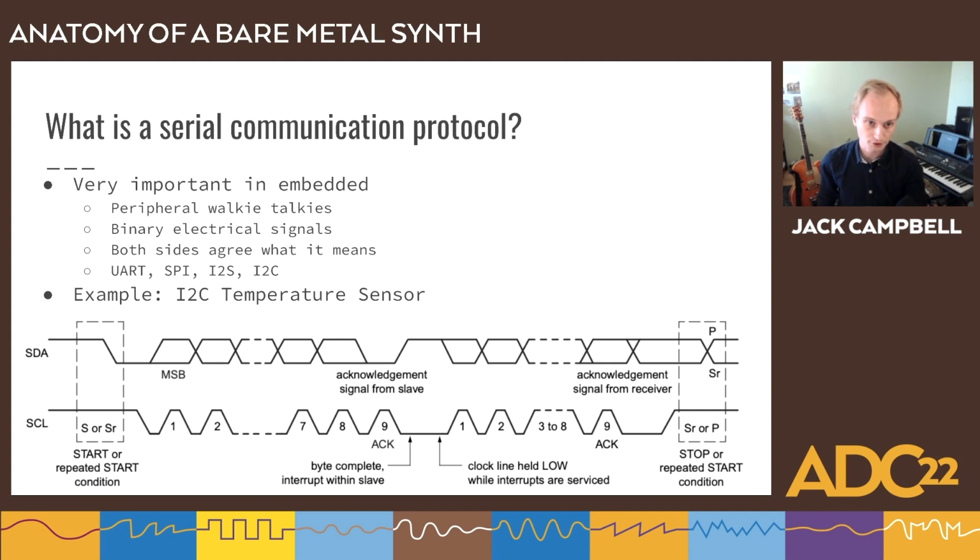So there will be 2 wires coming out of this temperature sensor, for example, and then 2 wires going into your microcontroller. The top line is the data line with the actual temperature data in bytes, or potentially integers. It depends on the bit depth of what you're sending over, but it's got the actual data. So it's telling you temperatures in Celsius.